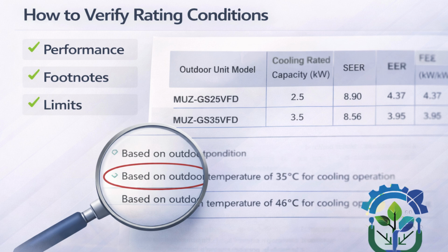See, due to this, the room will never reach its set point. Okay, the AC runs continuously, which will turn into higher DEWA or SEWA bills. The compressor would trip on high pressures, and the equipment would fail very early. Instead of serving its life of 10 years, it would serve just 2 to 3 years, and that's it. This is not an equipment defect. This is not a wrong design condition. This is actually wrong selection, you would say.